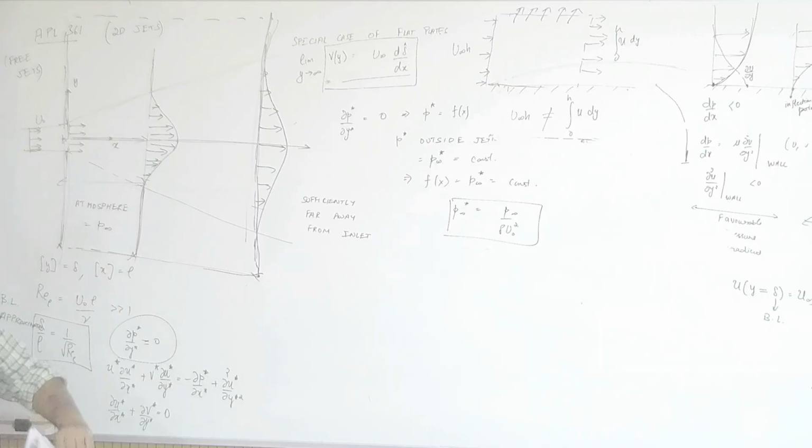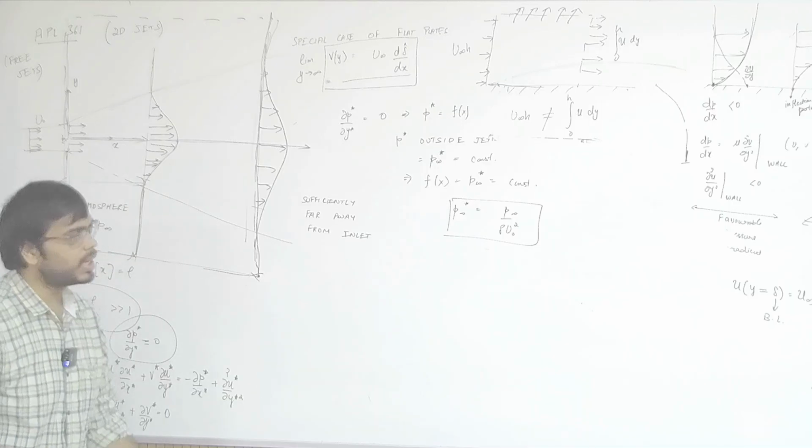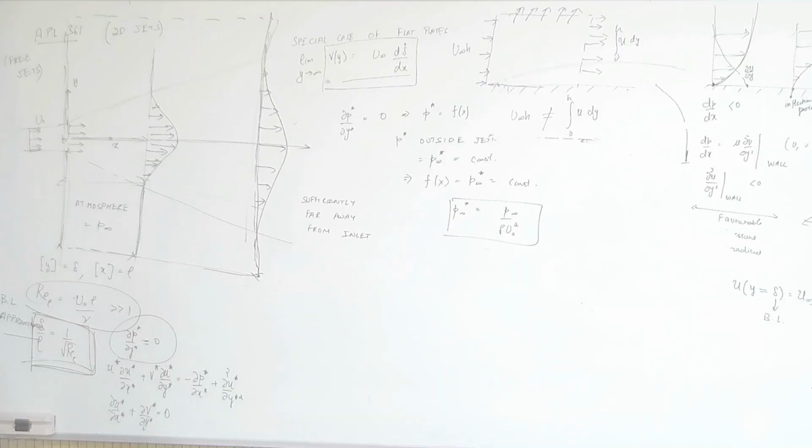Okay, by moving sufficiently far away you can make this condition always valid. It is actually more about this condition than this. Okay, this can always be satisfied. It is more about this condition. Boundary layer approximation is a combination of these two. It's not just high Reynolds number, it's a combination of these two, and that's what I'm trying to say, that we can actually apply this, the combination of these two, which are the boundary layer approximations, in seemingly unrelated flows as well.